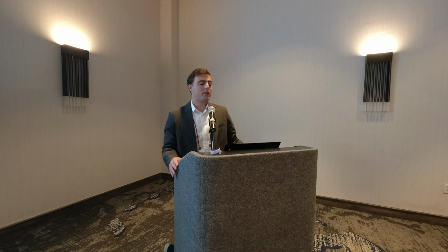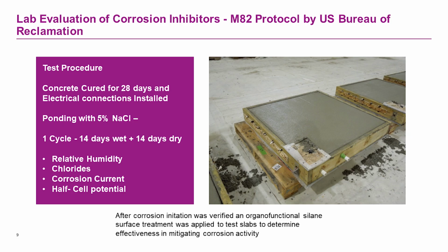These slabs are then ponded with a 5% sodium chloride salt solution for 14 days on, 14 days off on continuous cycles. So one cycle takes 28 days, about a month, to test. And again, no inhibitors added, nothing like that.